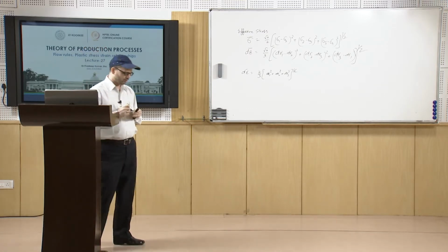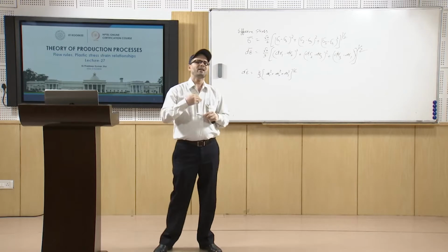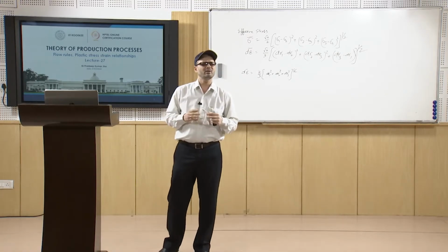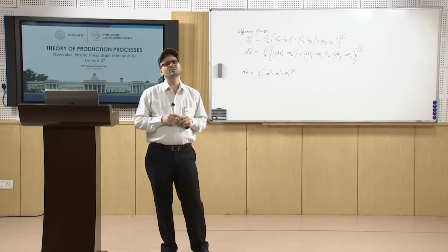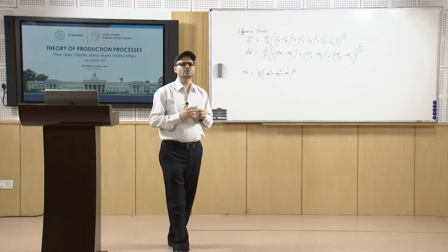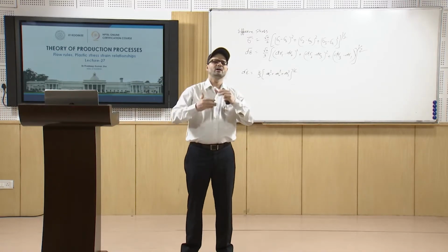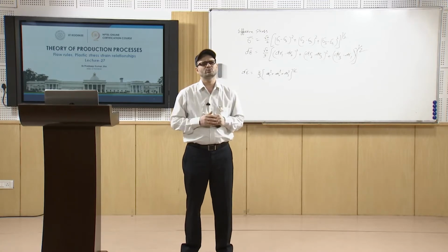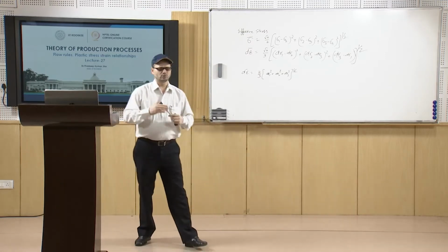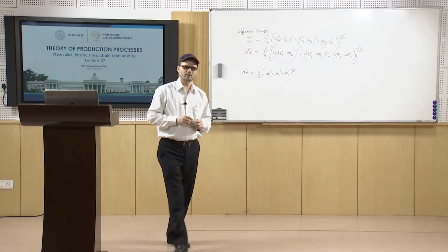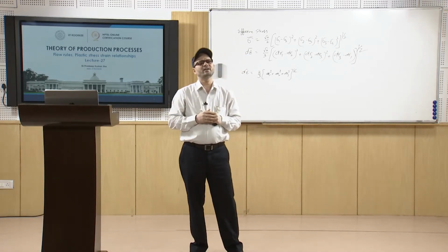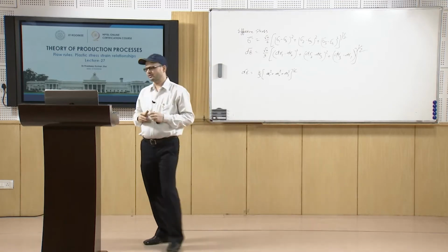Now, we are going to discuss the plastic stress strain relationships. We know that in the case of plastic deformation, the strain depends on the entire history of loading. So, it is necessary for us to know the increments of plastic strain through the loading path, how the increment is going on. In that case, we can have the total strain by integration or summation.